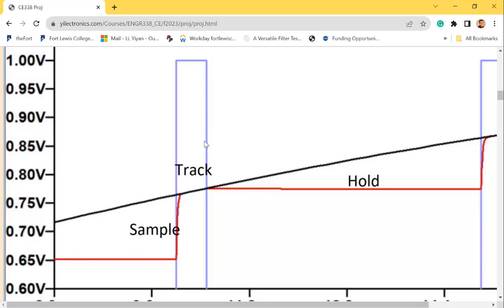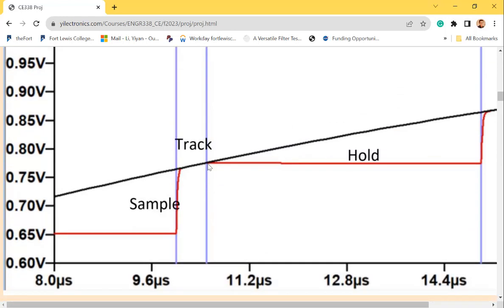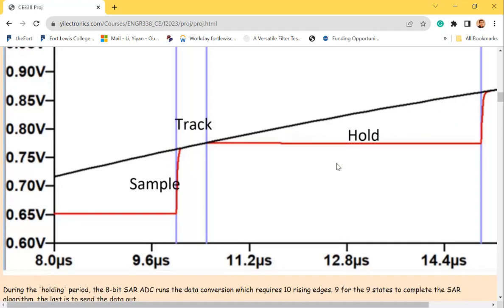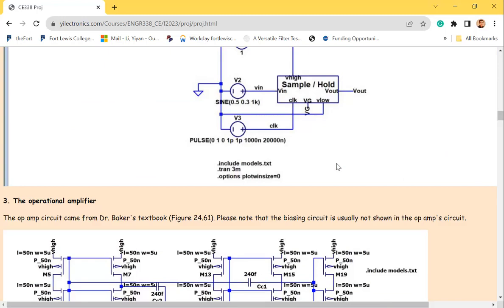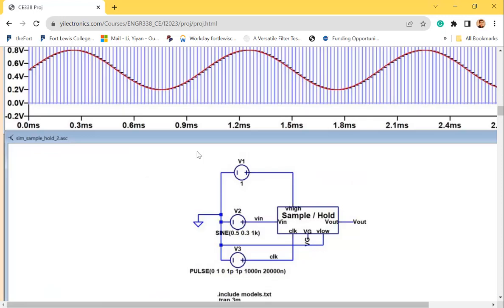And then you put it down to ground, it's going to hold it. So after it's being put down to ground, the conversion should start from here. You agree with that? Because it's a DC voltage being held over there. It's ready for the conversion. So we need to create a clock like this in the circuit. We have been doing the clock, which is 50% duty cycle. So we'll talk about how we generate this kind of clock in the circuit a little bit.